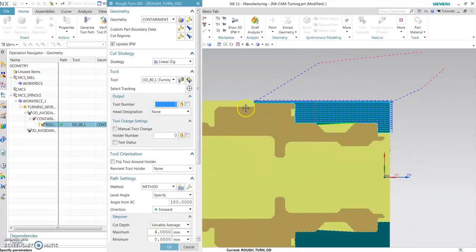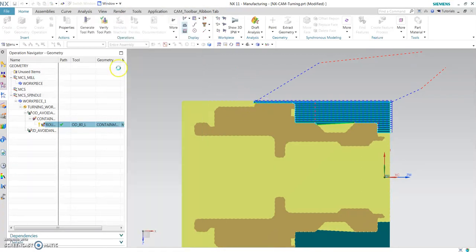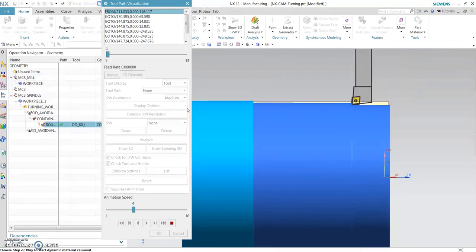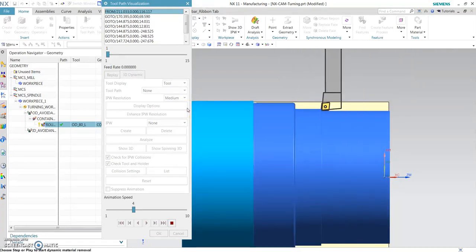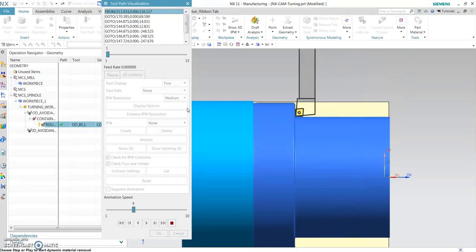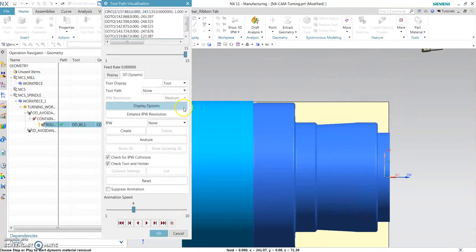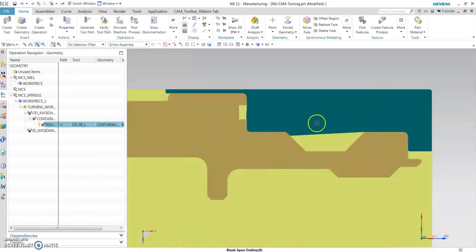Okay. So we got the lathe spindle right about here. So the tools are stopping right here as we selected in the containment, the axial trim plane. Let's verify the toolpath. Okay, that's exact just right there. We don't want the OD tool, particularly this tool.